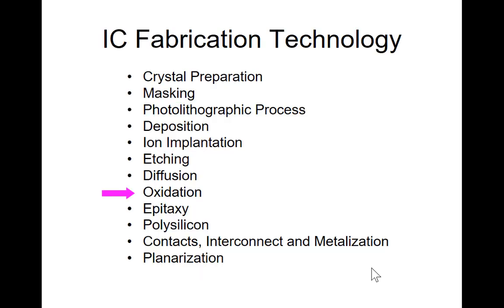So another step that is used is oxidation. The oxide is again used for separating, for isolation. Silicon dioxide is an excellent insulator, very good, better than many of the insulators you have seen. So you use it to isolate things, for electrical isolation, and it's used throughout the circuit.